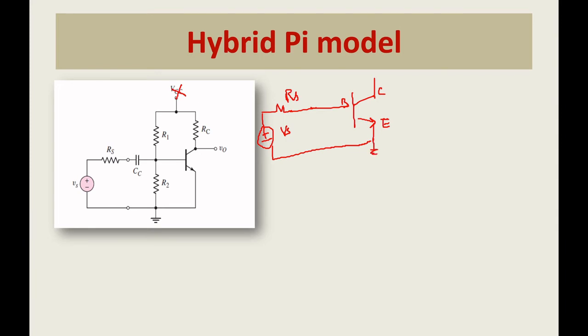Grounded. Now if I remove this VCC, this R1 will come to the ground, right? The passive elements will come to the ground. That means R2 and R1 will become parallel, right? I am repeating again, I am removing this VCC so that R1 will be connected to this ground. Here in RC, this is also removed, so this RC will also be connected to the ground. Here you are taking your output point, that's all. What is the next step?